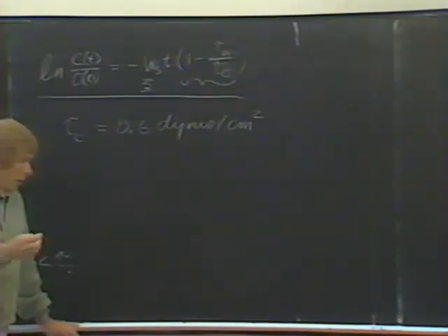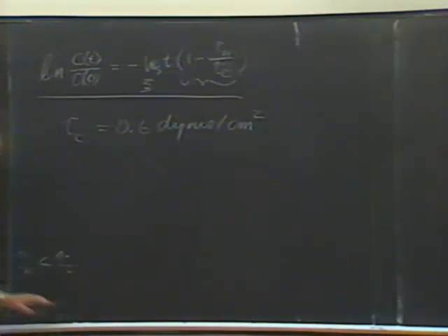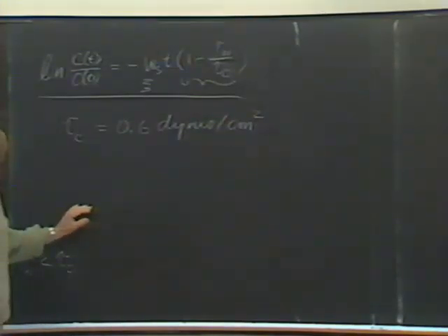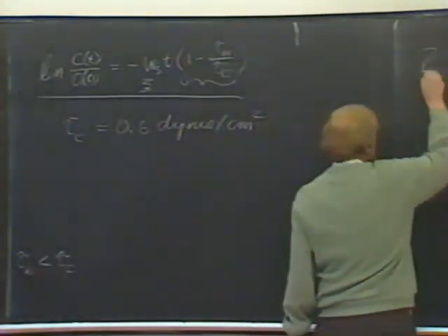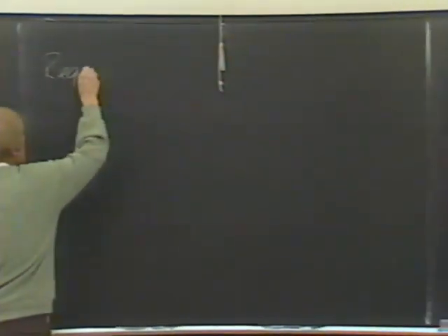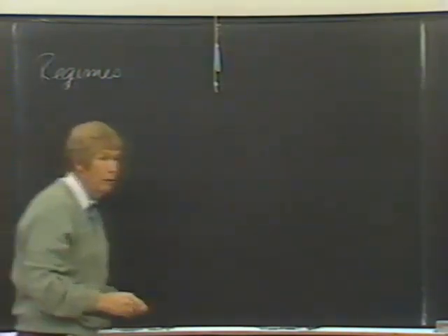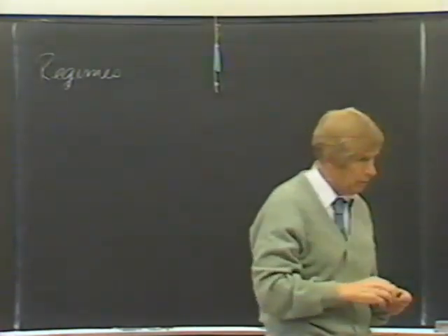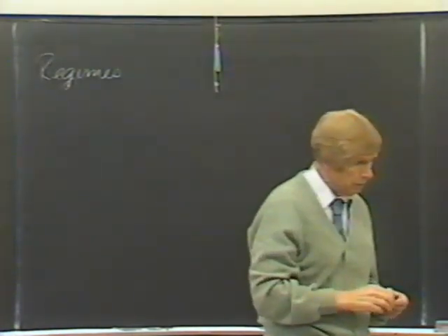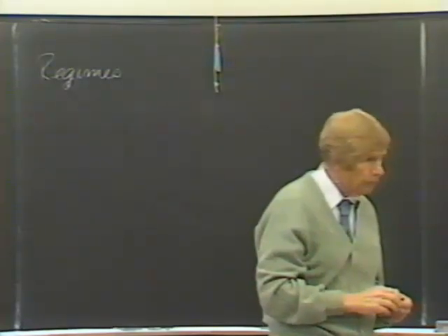It's a function of concentration and velocity gradient. That is the frequency of collisions. Remember, the frequency goes up with the concentration squared and with the velocity gradient. Then the third one, it's the same as this, but settling velocity is hindered. And it's a function of these things.